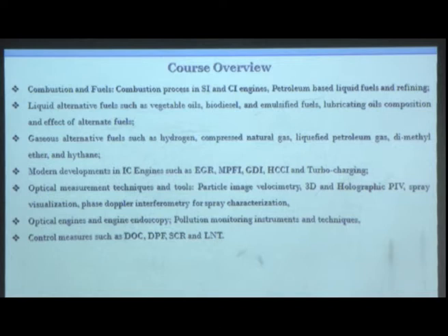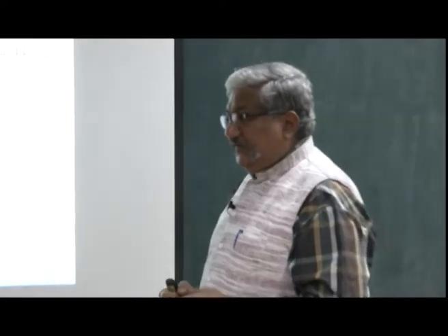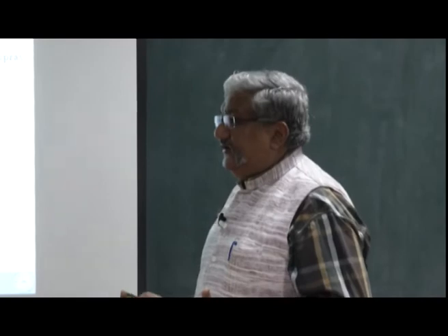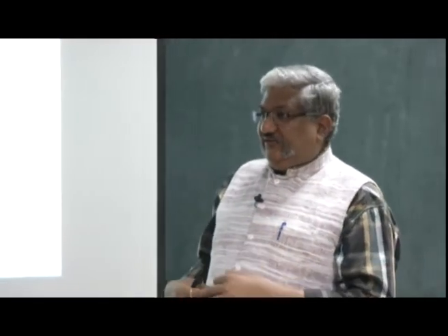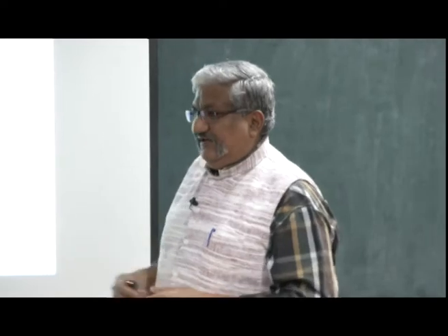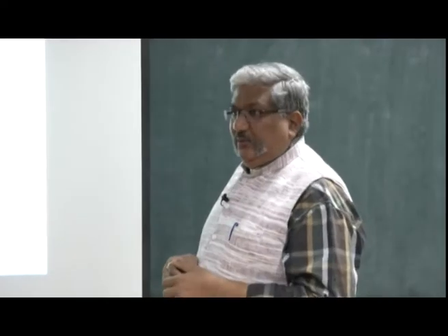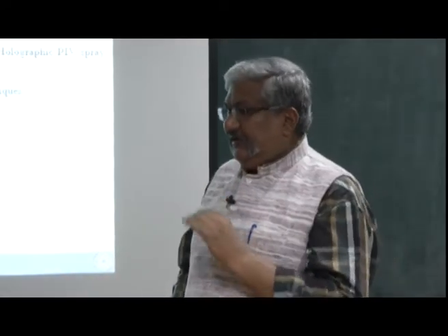And then I will be talking about engine endoscopy. So endoscopy, are you familiar with endoscopy? Endoscopy is a technique which is traditionally used in surgeries, in medical science, where you don't have to really cut yourself open, just make a small hole, put a camera inside, and do the surgery and take it out, and within a few hours or a few days you're able to recover. Okay. So basically a small hole to see inside in great detail. So that's what we do in the engines also.